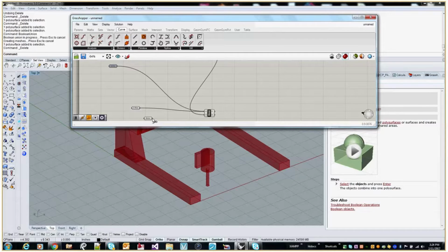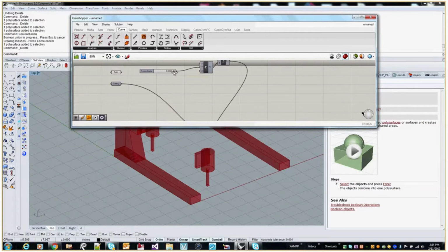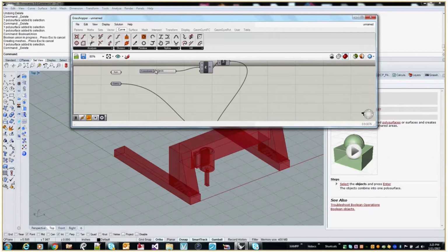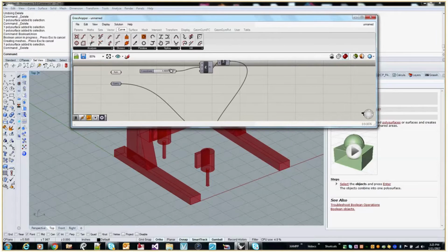If I were just to grab this and drop it, it dropped these other two. So you do what you want to do first. Then on the next ones, you hold shift, plug it in, and it'll just continuously add whatever you place into there. So we know that the Y movement is grabbing everything we want to move, which is the gantry, the Z plate, and the motor, all in one operation. And that's great. That's exactly what we need.